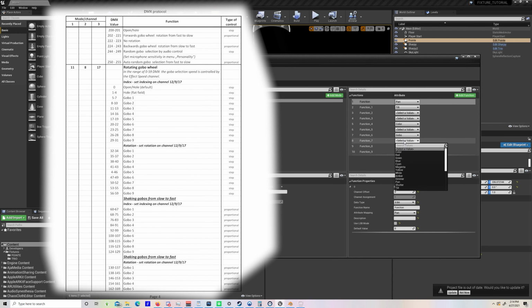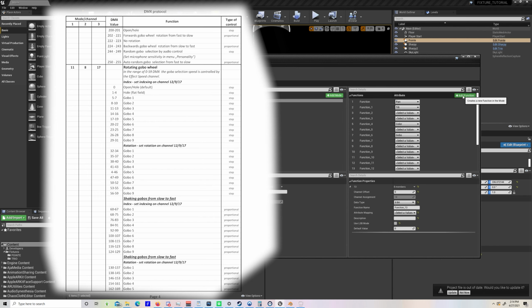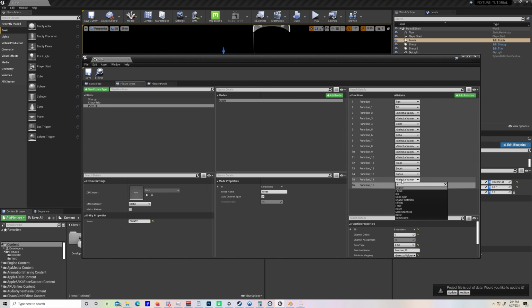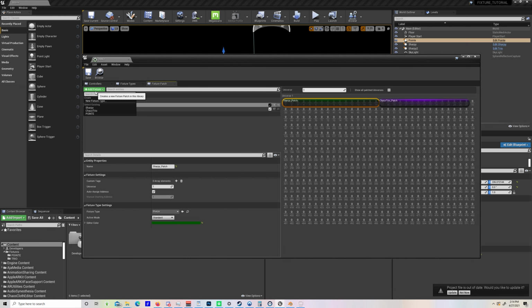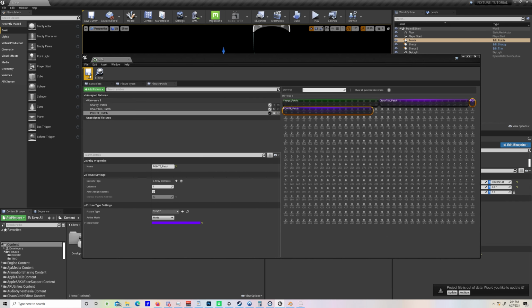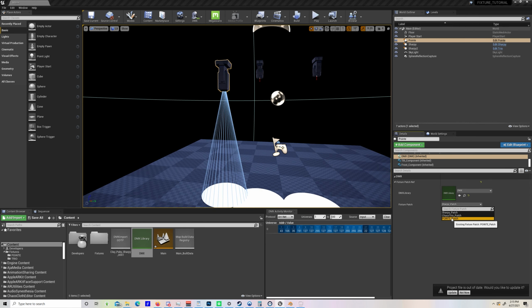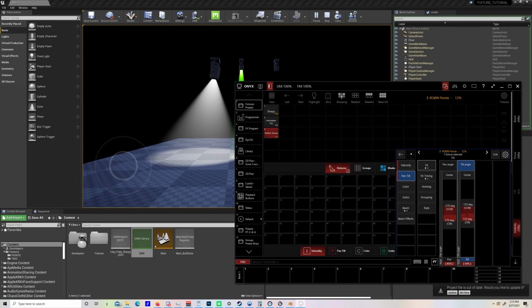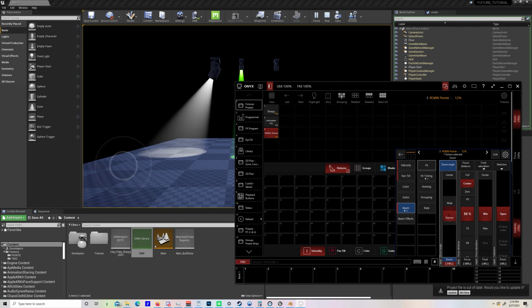You'll notice 2 gobos, and we're just going to ignore the second one for now. I could have chosen a better example light, but I didn't. Finish filling out your attributes. Add a point to your Unreal DMX library, then assign it to our fixture we placed in our scene earlier. We can see that we are able to control functions like dimmer, pan, tilt, and zoom correctly.